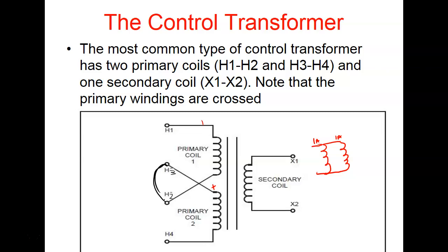And what we're going to shoot for is 120 volts over here, because all our components are rated at 120 volts in this class. But when we do the transformer lab, you're going to hook it up for divide by 4. You're going to start off by dividing by 2, then hook it up divide by 4, and you should see that when you hook it up divide by 4, your secondary voltage is going to be 1/2 of what you measured when you divided by 2, right?